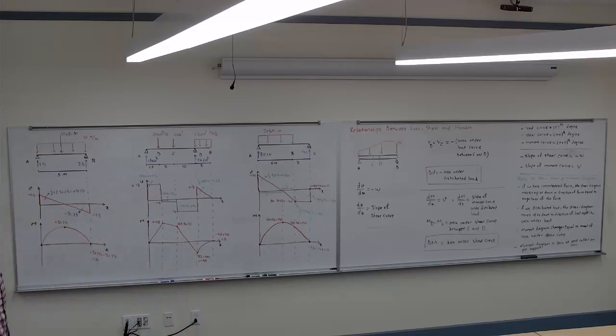I guess if our graph ended up having the middle one with the max at positive 18, and at one point it went to negative 20, wouldn't that put a stronger stress on the beam? We look at the maximum absolute value. Okay, so if it's negative, it's bending the other way. So it is the absolute value. So it's the maximum absolute value that we use for the design.